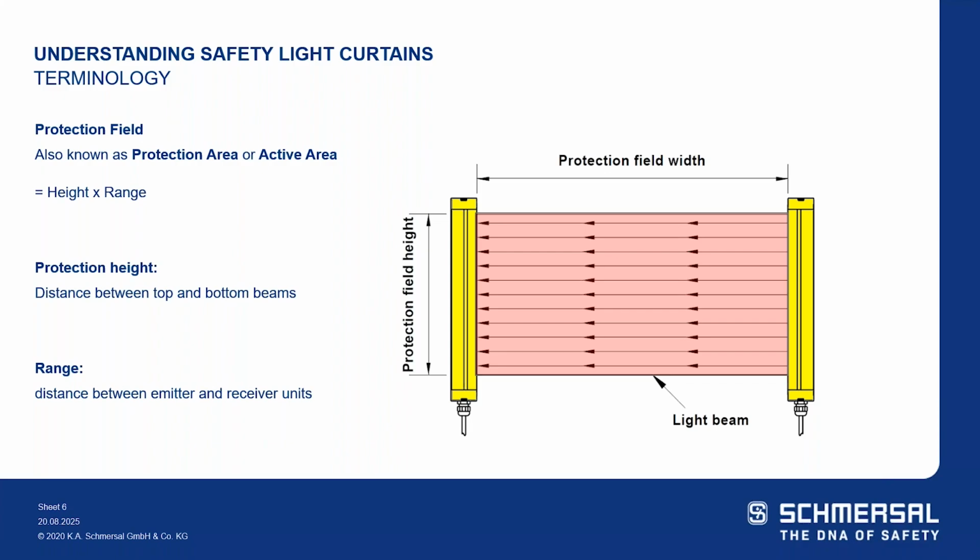The range, that's simply the operating range or the sensing distance between the emitter and the receiver. And that can vary greatly as well, dependent upon your resolution and dependent upon the device that you're looking at. Our current units can range from a close 12 inches of sensing distance to upwards of over 65 feet maximum, depending upon the resolution and other factors.